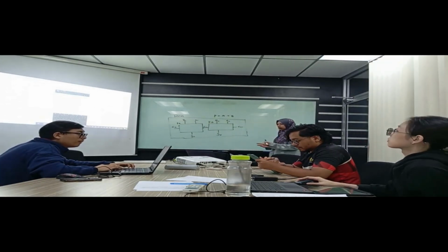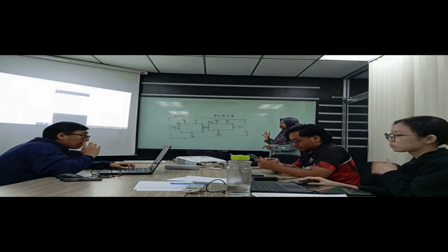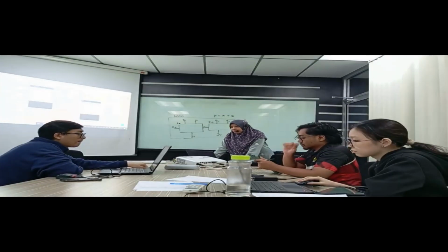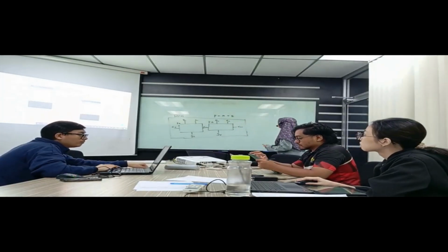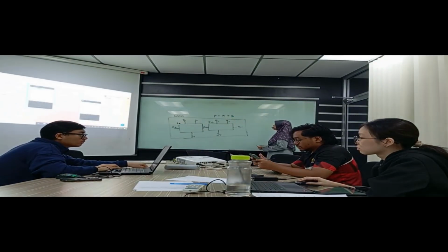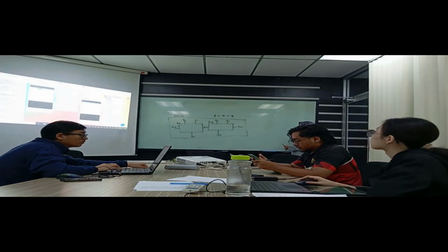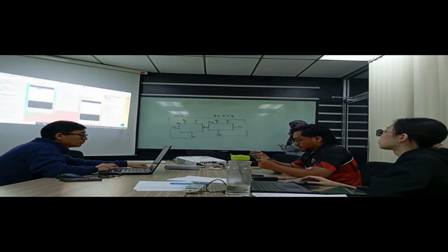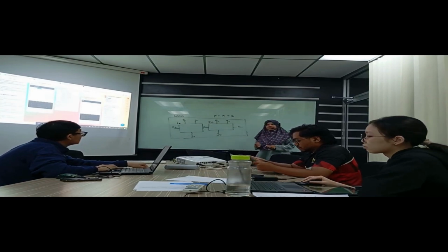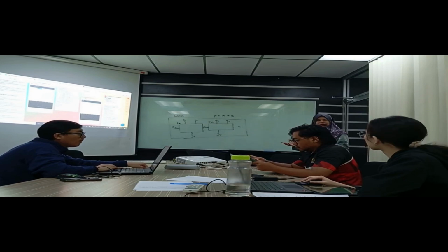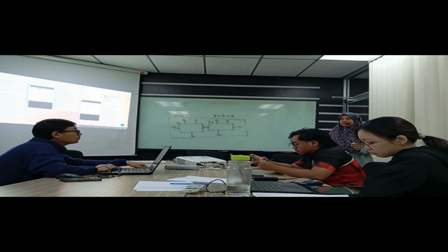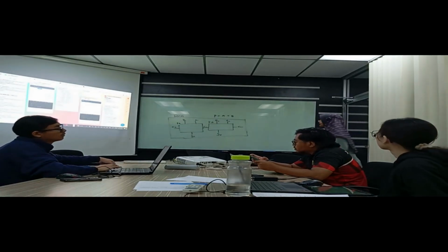Okay, alright. So now the question asks to change or modify it using data flow modeling. Now you know this is F equals A plus B, and A and B are the bits that you use now. So data flow modeling actually represents the Boolean equation, right? What is the keyword for data flow modeling? Assign. Okay, very good.